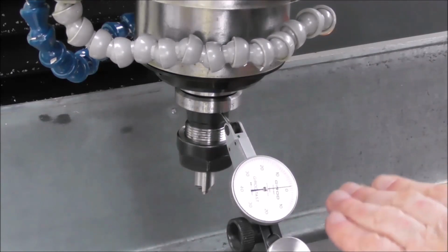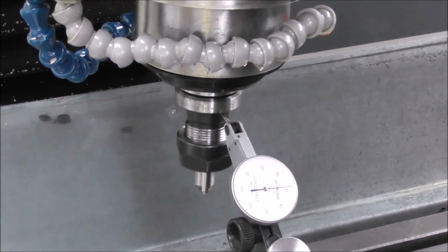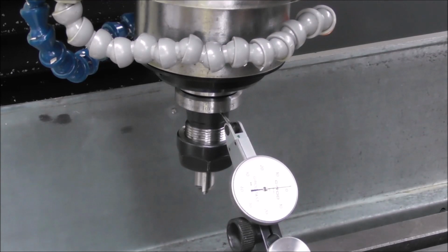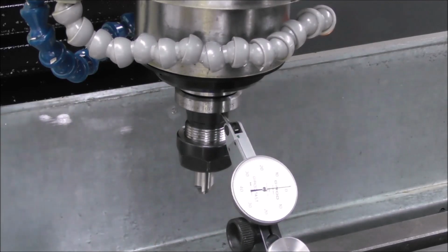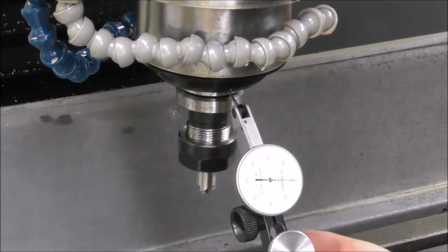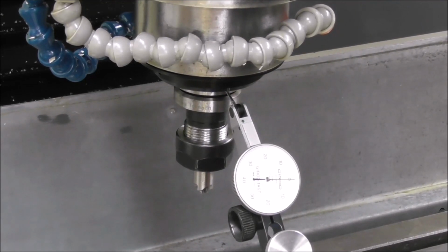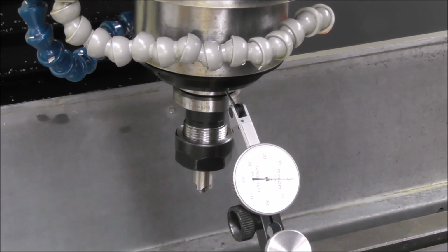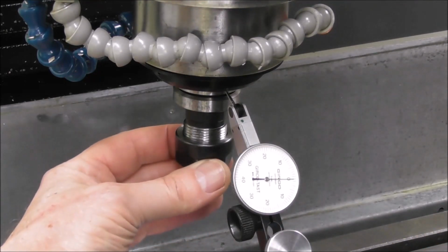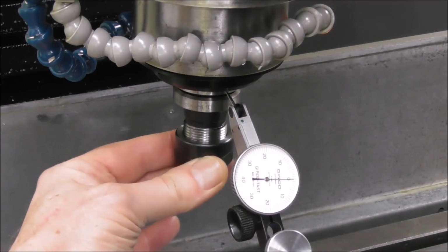So you're getting a movement of your TTS, and that movement is coming from a compression of the TTS flange and a compression of the spindle itself. I'll just show you a breakdown of that. I've moved the dial indicator now to the end of the spindle nose. So we know from the last measurement that we're getting just over 2/100ths of a millimeter movement under drawbar tension. That's about a thou. Now how much of that is spindle compression and how much is TTS flange compression?